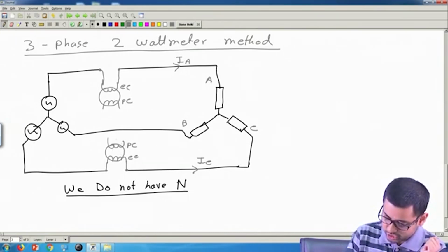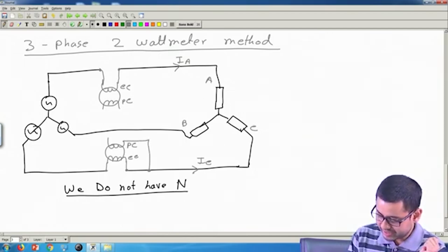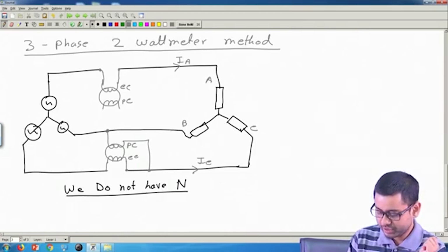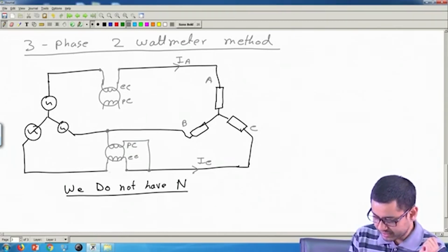between the corresponding say line. So, this is measuring line current in phase C, line current C. So, we will measure the voltage between C and the unused line, which is B. So, this will measure the voltage between the corresponding line and the unused one.